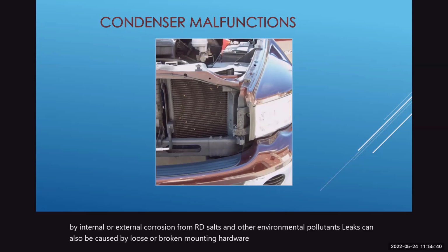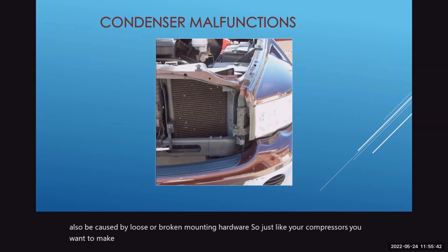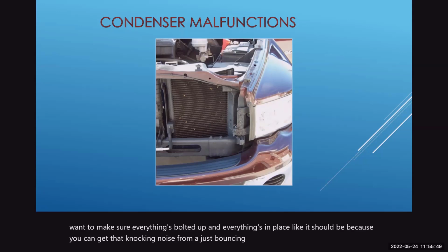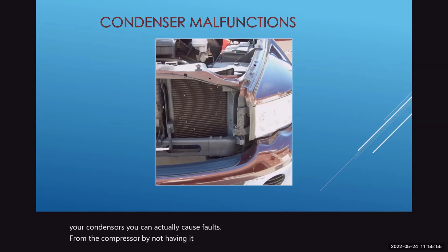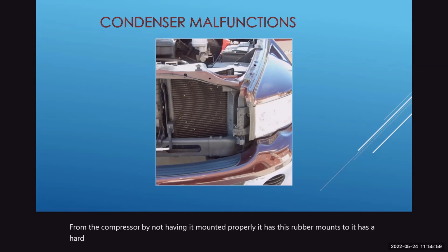So just like your compressors, you want to make sure everything's bolted up and in place like it should be, because you can get that knocking noise from it just bouncing around. Also, with your condensers, you can cause faults by not having it mounted properly. It has rubber mounts, and hard mounts usually on the top, or it might have a rubber mount on the top too. That's to keep out any kind of vibration that might damage it.